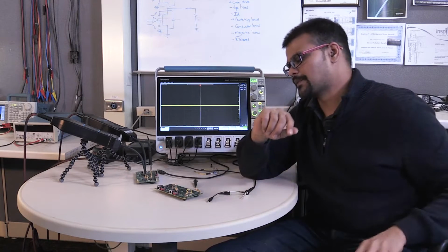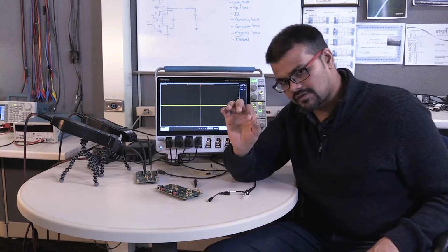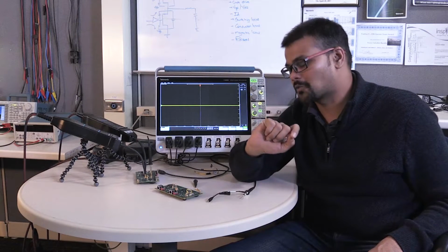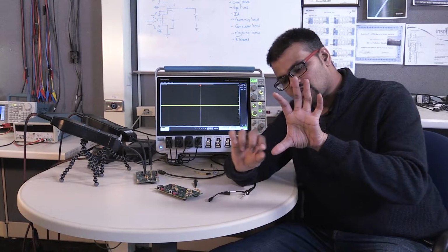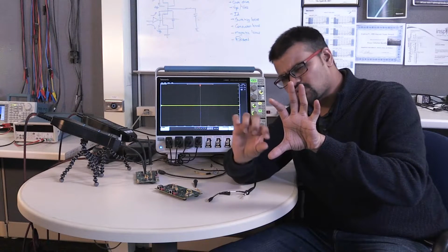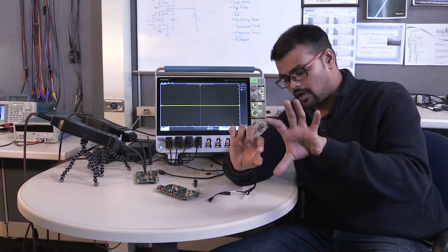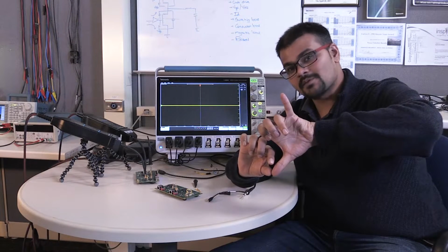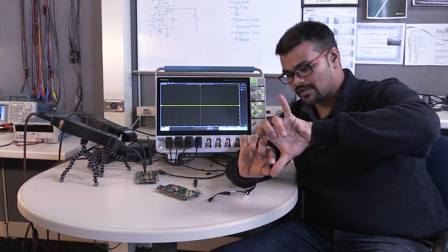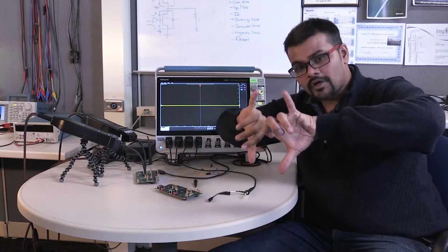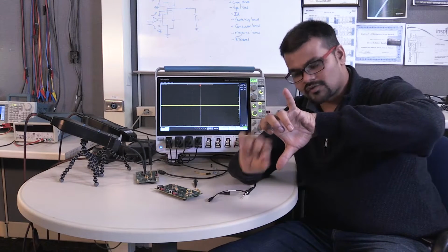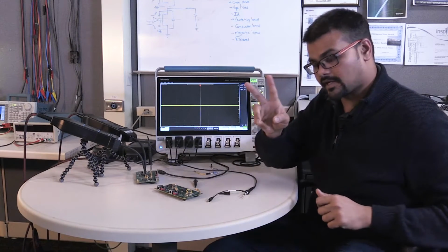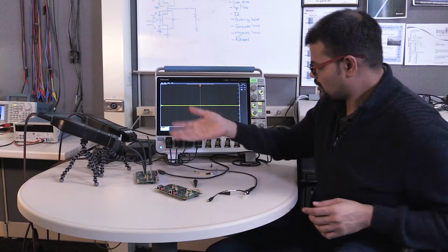I'll give you another example. Think about conduction losses or switching losses, and think about the RDS(on) measurement, which is another hot one. The RDS(on) measurement is in the conduction area, which is really small, usually in millivolts depending on your RDS(on), and you're looking at it in presence of a VDS measurement that can be 400 or 600 volts. So you really need the vertical resolution, the number of bits, to resolve that to get decent accuracy from that measurement. So 12 bits is the second reason, and the third reason is sheer number of channels.